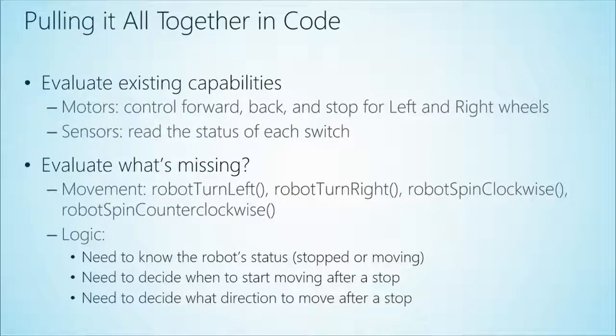Because this guy's going to go into a spot and it's going to try and back up, basically, but it needs to turn a certain way. So depending on which of the sensors is up against the wall, it's going to take that into account as it goes. It's also going to look at how much time has gone by since it's trying to maneuver out of that position. So if it moves, hits its front right side bumper, and starts backing out a little bit to the right, and it hits its rear right side bumper, it's like, oh man, it thinks I'm in a corner. I need to figure out another way, and maybe it spins or does something. So those are the kinds of things you need to think about.